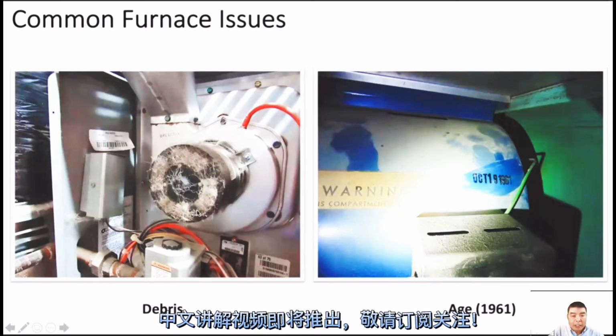If the customer just uses the cheapest filter you can get from Home Depot, maybe $10 for 3, it cannot block the dust. Then most of the dust collects at the end of the motor, like this motor and the other motor. That's not good, so you should recommend the customer change to better filters. I think we will talk about the filter later.